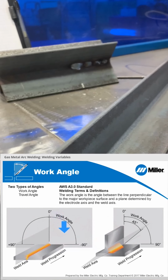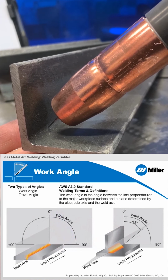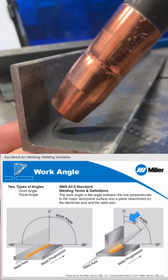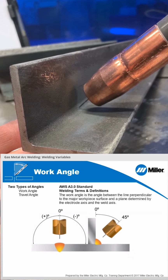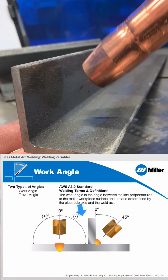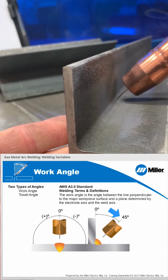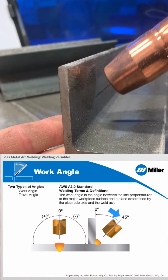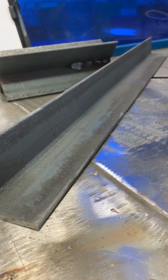Another example of this on a T-joint, this gives me the ability to place the arc exactly where I want to have my penetration profile and how I want to fill in the metal. It's extremely important if I'm doing any multi-stack welding where I have to position the gun in different work angles to be able to stack. But in this case, if I'm coming down this 90-degree, I'm going to keep a 45-degree work angle the entire time with it. That is how we explain work angle.